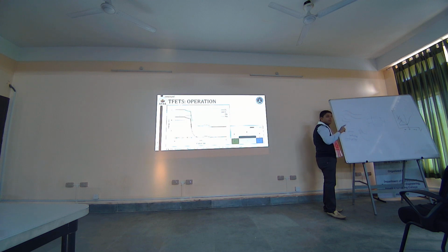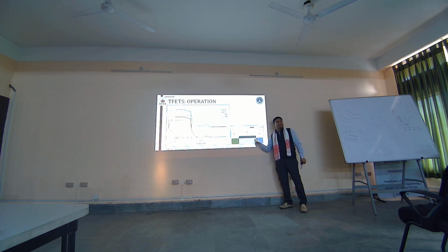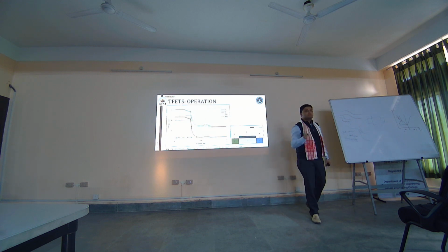Now my problem is with the drain side of my device, because this is where my ambipolarity is going to occur. So it means I will have to look at changing the doping concentration on the drain. Are you getting my point? Yes? Am I able to reach out to you?